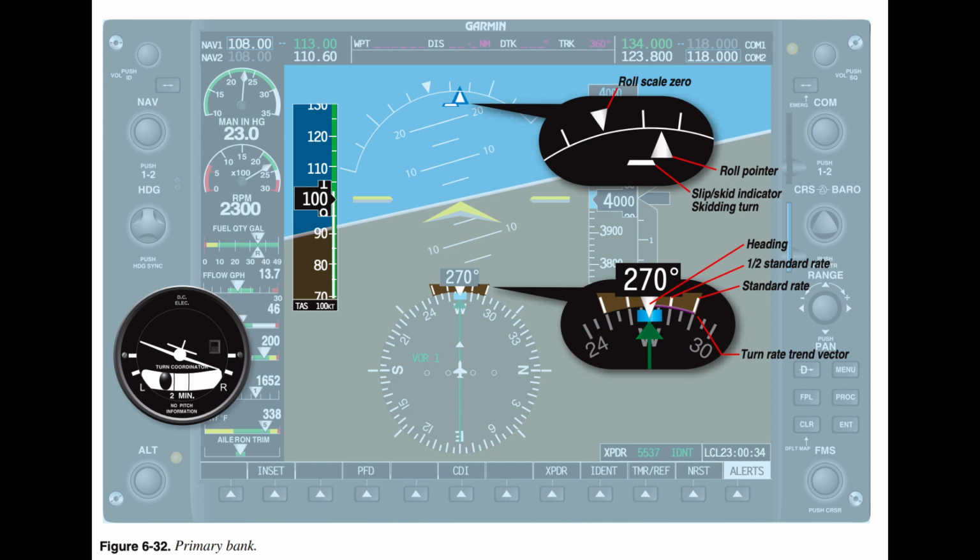Scanning techniques. Since most of the primary and supporting aircraft attitude information is displayed on the PFD, standard scanning techniques can be utilized. It is important to remember to include the standby flight instruments as well as the engine indications in the scan. Due to the size of the attitude instrument display, scanning techniques have been simplified because the attitude indicator is never out of peripheral view.